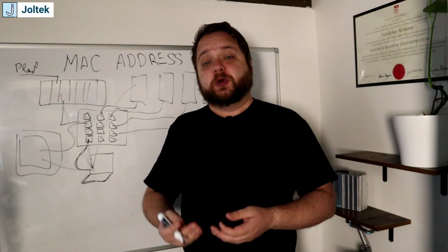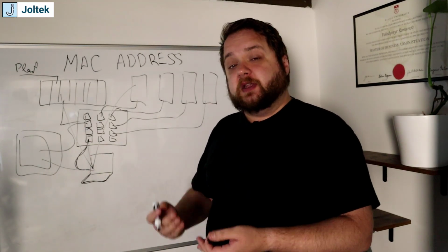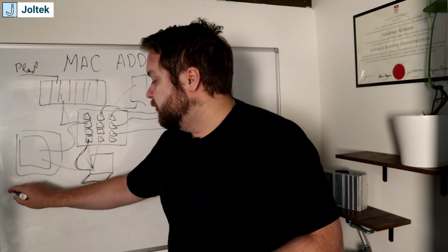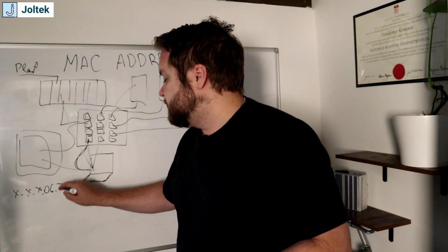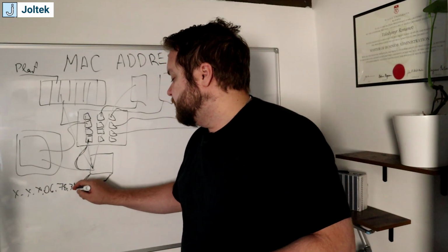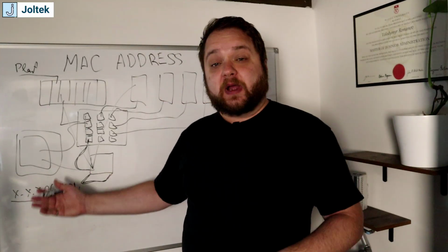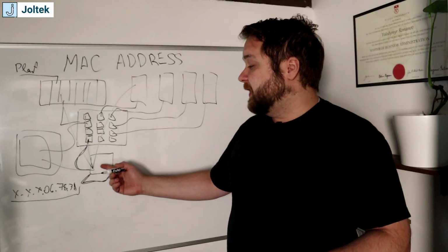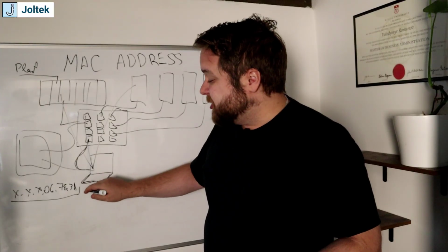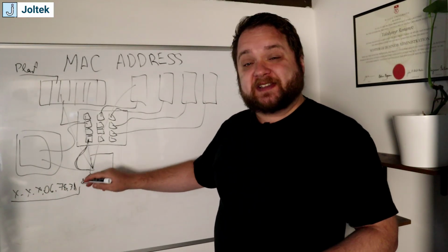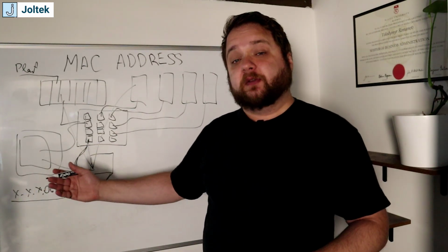So to avoid that, what you can do is go to the HMI physically and locate the MAC address, right? So again, you're going to have some kind of identifier, 06.78.38, as an example. Usually I would take a picture of this or write it down in a notebook. I would go back to the station that is seeing a lot of different addresses, and I will make sure that the IP address I'm assigning to a specific device matches the MAC address specified on the device, right?